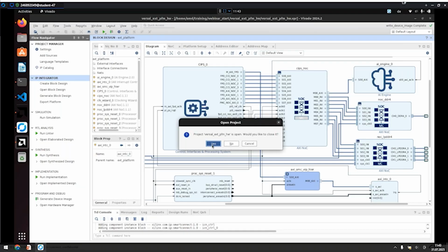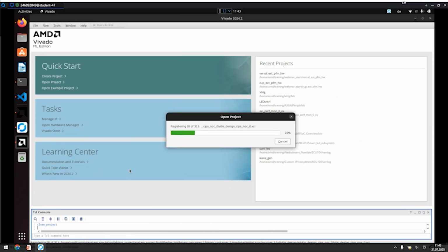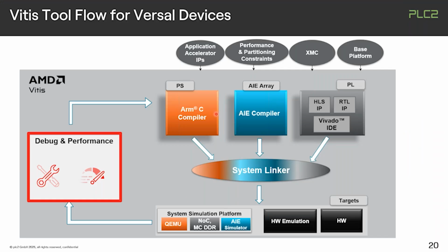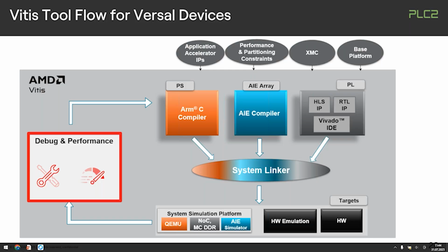The system level project, this redefinition of things, brings the new top level into a new Vivado design. So basically this complete software design flow that we were showing before will define a new top level by the aggregation of these different elements. And you will then use Vitis to create a new top level that gets fed into a Vivado build under the hood. So what we are doing is kind of a remote controlled change to your particular items.